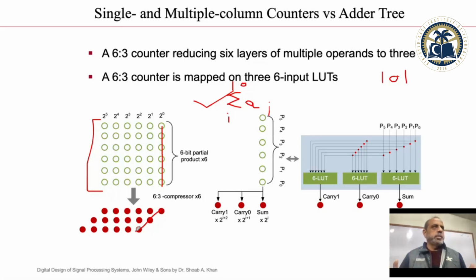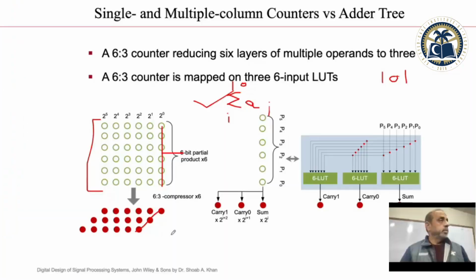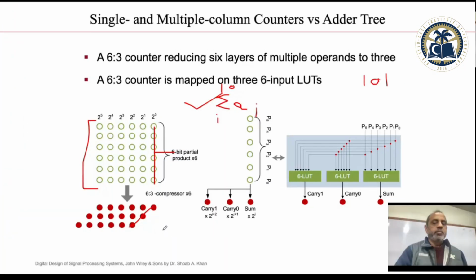Right? So the same concept. Instead of just a full adder, you have a logic which will take 5 numbers and just add them together. Using some logic, maybe a lookup table, it is going to generate 3 bits. We put those 3 bits like this. So directly from 5 bits, you get into 3 bits. Right? 5 bits gets compressed into 3 bits, because this is the worst that you can get.